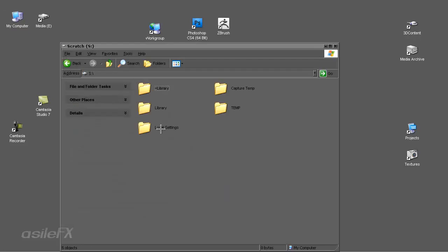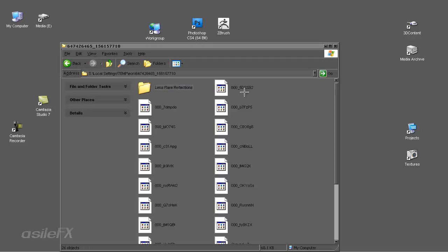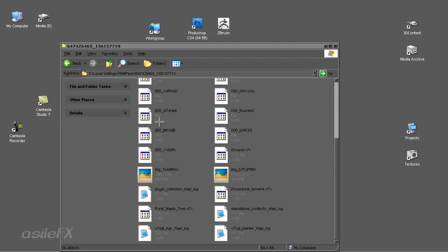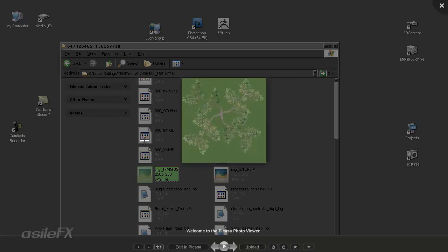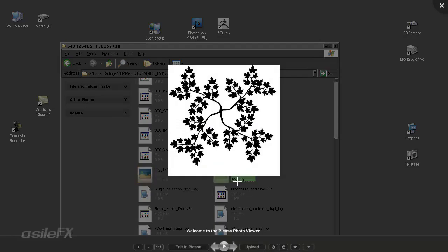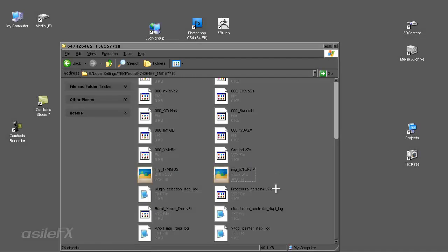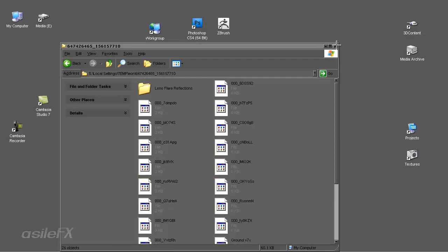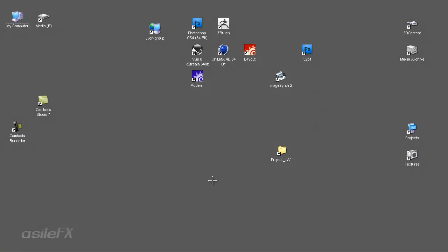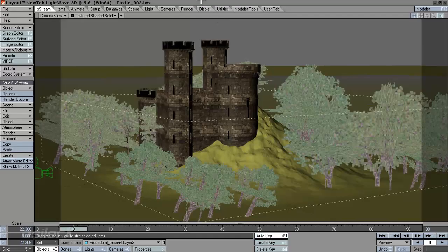So that is where everything is saved to, in an Eon folder, and you'll be able to see all of the generated files where we have the images that are transferred over, also any sort of temporary scenes. It's all saved to that folder. So things can run a little more efficiently if you set that temporary folder to a designated scratch disk.